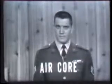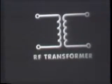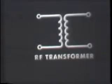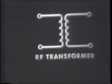Well, at frequencies above 20,000 cycles per second, the RF transformer comes into use. At these frequencies, hysteresis and eddy current losses in an iron core become so great they have to be prevented. Therefore, RF transformers generally have an air core. The schematic symbol for an RF transformer, then, is easily identified by there being no vertical lines between the primary and the secondary coils.